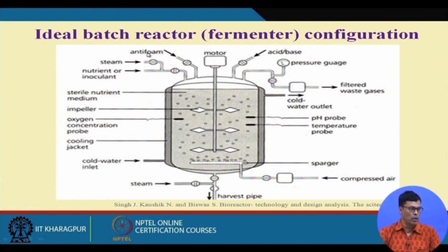So we use antifoam oil. We put a sensor here. As soon as the foam touches the sensor, it is connected with a pump, which is connected with an antifoam oil tank, and that will drag the antifoam into the fermenter, so that your foam will subside.